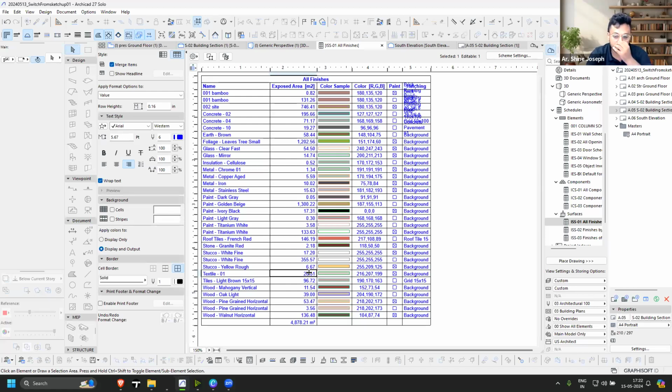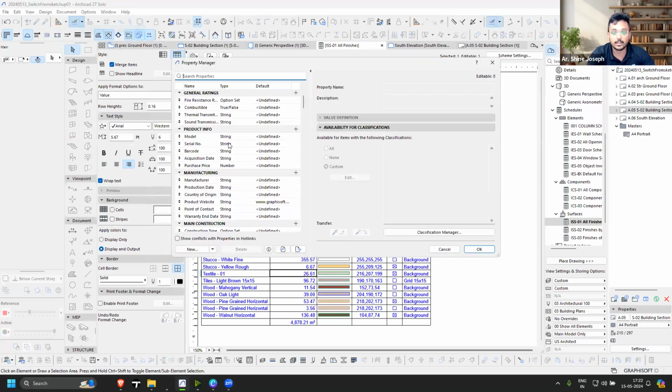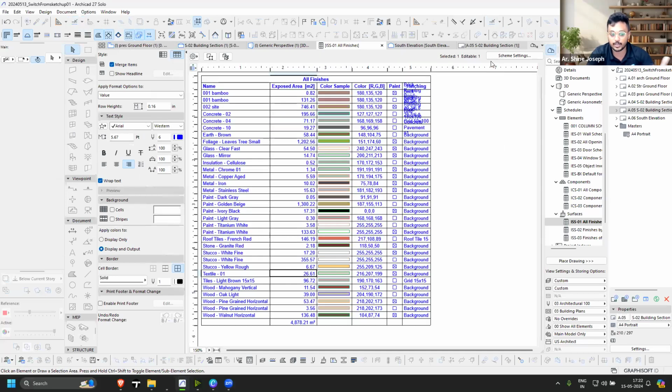If you want to convert that completely into something like how many tiles, you just divide it by that particular tile size. We have a specific thing called property manager. This property manager will let you create certain types of things, for example, calculating this tile. In that we assign those particular equations, and it will give us the output of how many tiles or how many bricks are required. We'll be looking a bit more into the property manager in the coming session.